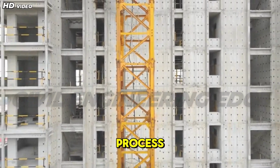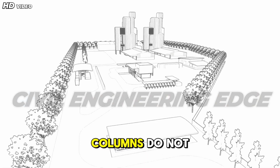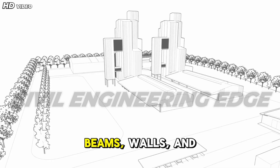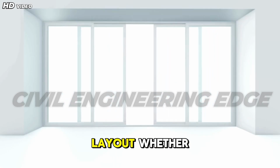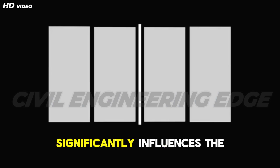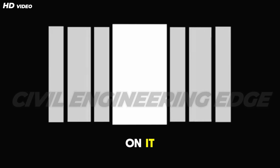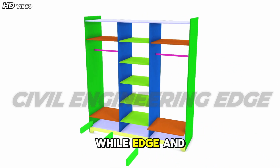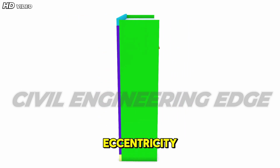The column design process begins with understanding the structural system of the building. Columns do not work in isolation. They interact with slabs, beams, walls, and foundations. The position of a column within the structural layout, whether it is a corner column, edge column, or interior column, significantly influences the magnitude and type of forces acting on it. Interior columns typically carry higher axial loads, while edge and corner columns experience greater bending moments due to eccentricity.